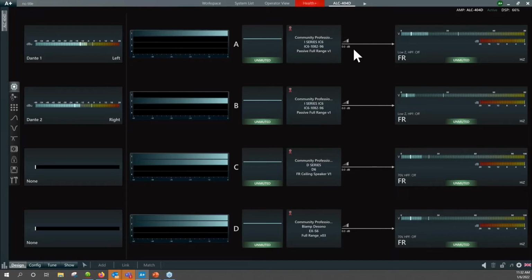And a lot of times guys get on site and are not getting any output. Check your attenuation knobs. Somebody might have touched them. When you're in Harmonia Plus, you can see those knobs. They're set to 0. That means they're at full volume. All right. Okay, I'm going to mute these again. Simple system.